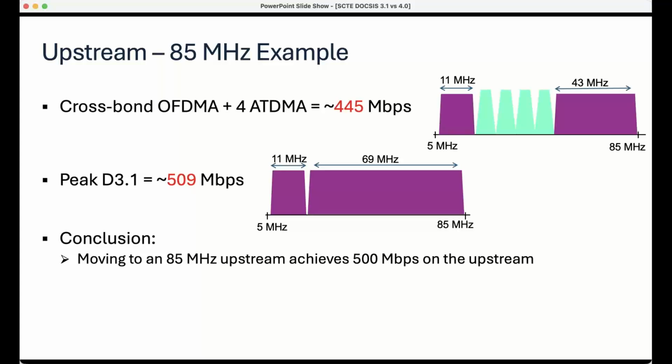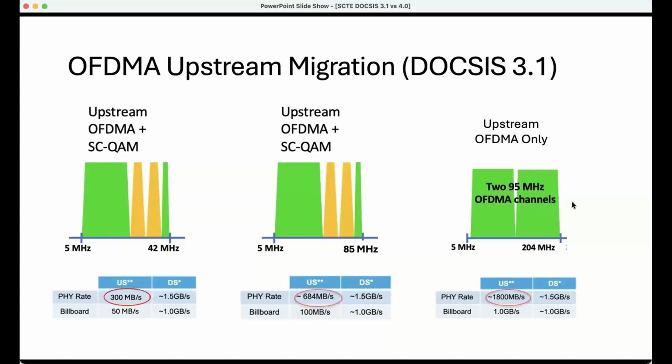Of course, the best solution would be to deploy a technology called the profile management application, which would adjust the modulation across this entire band automatically, dependent on exactly where the noise is. But that's an entirely different presentation to get into how profile management application works. There will be a couple presentations at SCTE Expo this year, if anyone's attending, that talk about how PMA works, particularly in a DOCSIS 4.0 network.